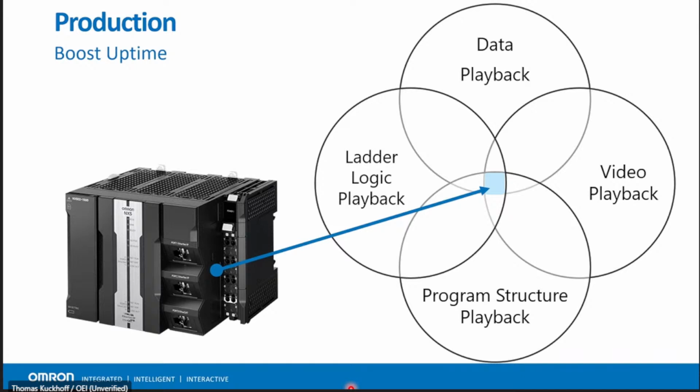And the NX5 now has the ability to play back variable data, ladder logic, and video, up to 15 minutes of it, whenever an event is recorded. And that event recording can be built into the program itself. So if an event occurs or if something needs to be recorded when nobody is around, the controller itself can record that data. And we're showing this convergence of playback from ladder logic, variable data, and video, because once